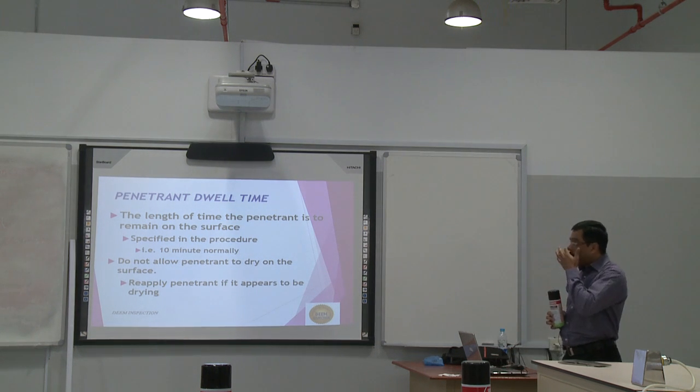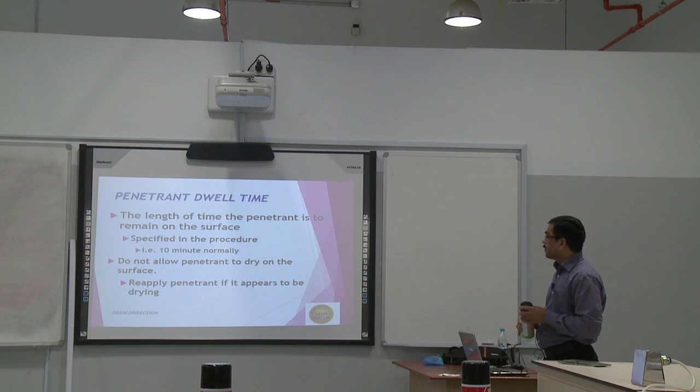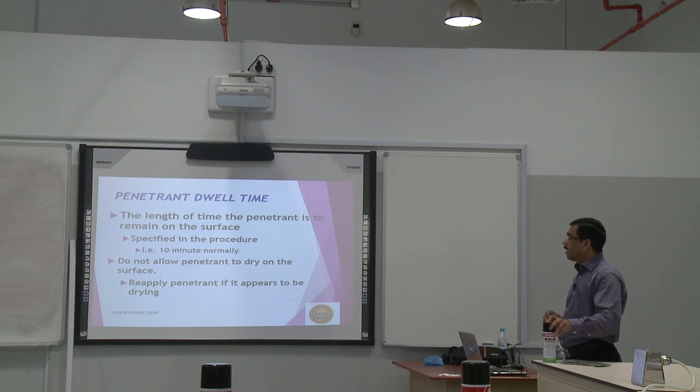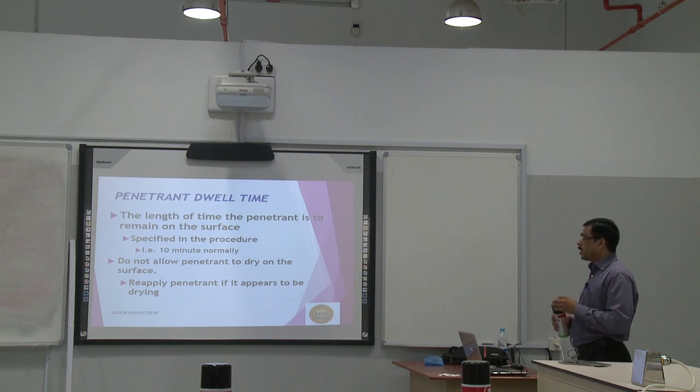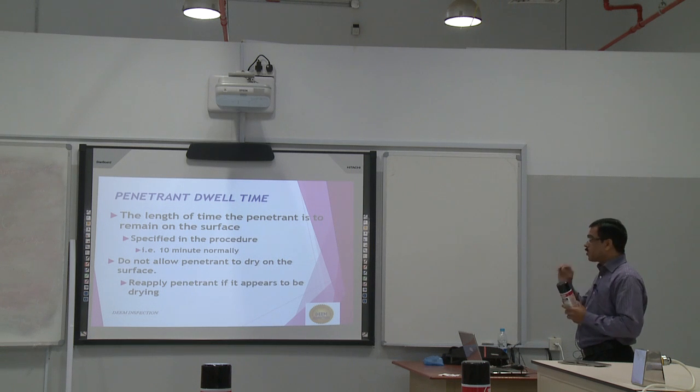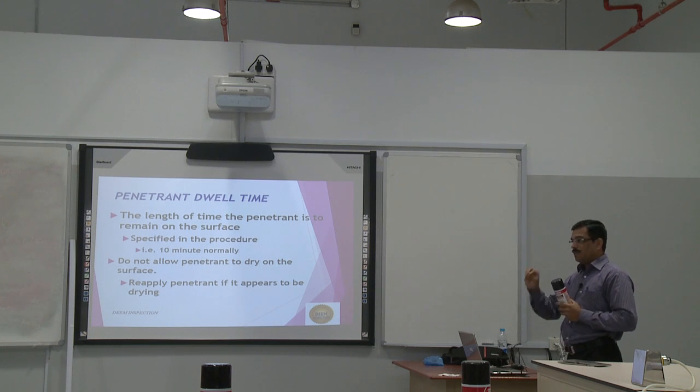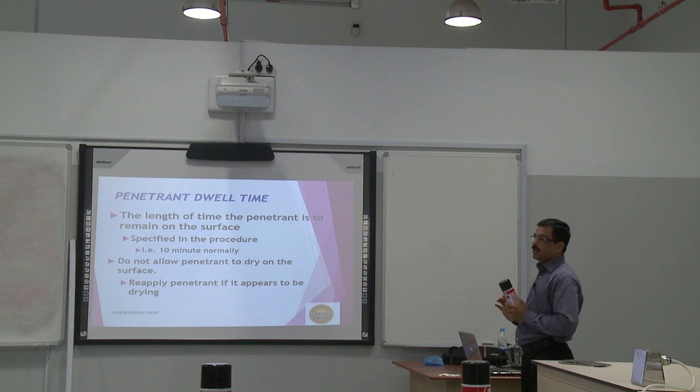What is the dwell time? It is the length of time the penetrant is to remain on the surface. We are calling it a dwell time. Usually it is specified in the procedure. Wherever we are doing any NDT method, there will be one procedure, and this procedure mentions how much time we have to give as the dwell time.